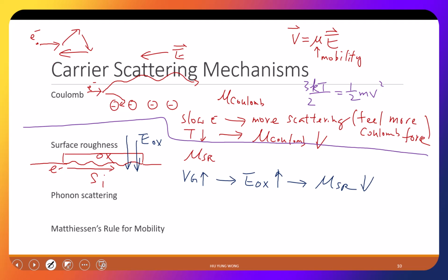Smaller. Yeah? But we want to have a high Vg, right? Remember our device, we want to turn it on. Remember the transconductance? I don't have the slide now. If you go up the ID-VG curve, you have larger transconductance. Correct? So that is not good.